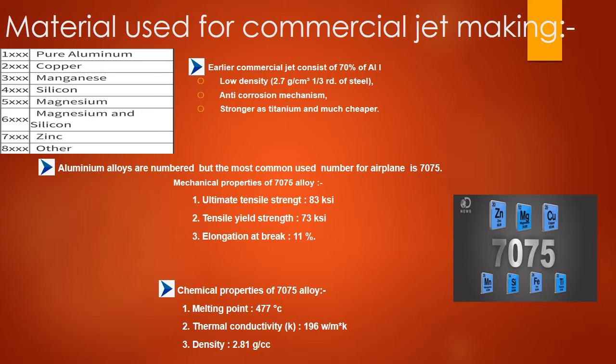According to the given figure, the numbering is done on the basis of alloying elements. For example, 1XXX indicates the most pure aluminium alloys, whereas 6XXX represents a significant amount of magnesium and silicon that has been added to the aluminium. The second digit represents a specific modification to one of the alloying elements. The third and fourth digits are used to label the specific alloys.